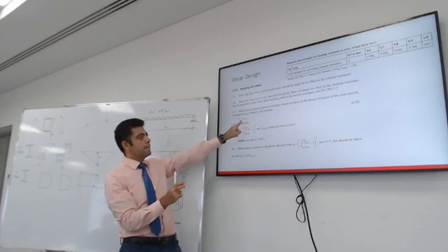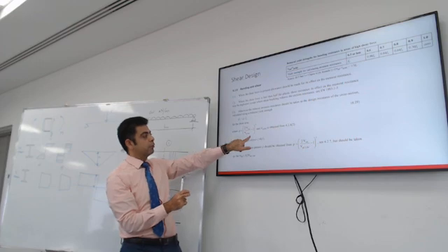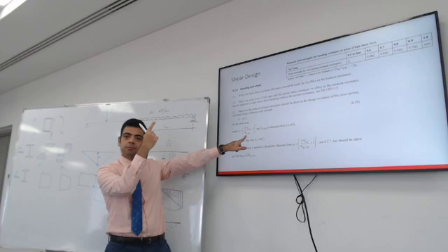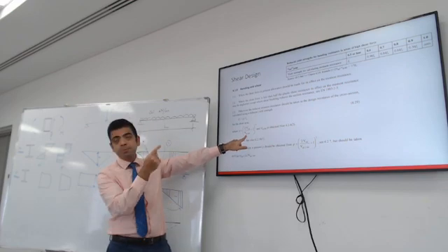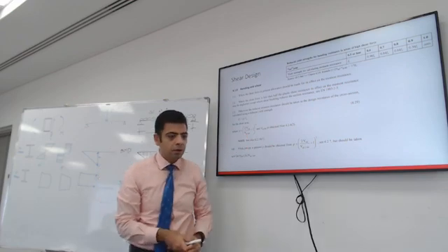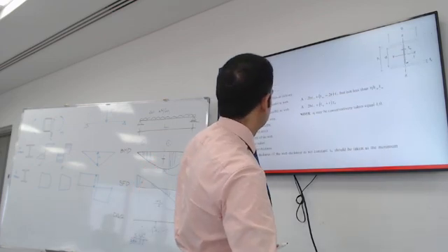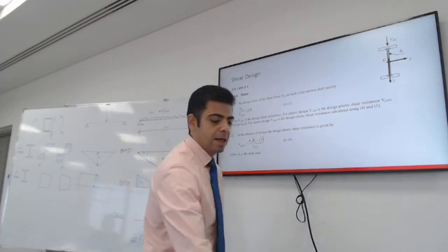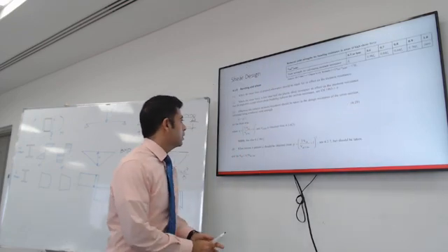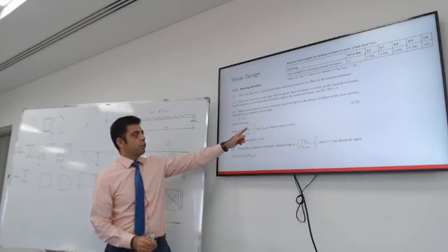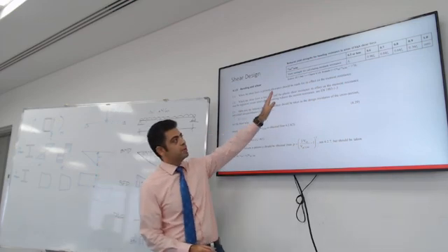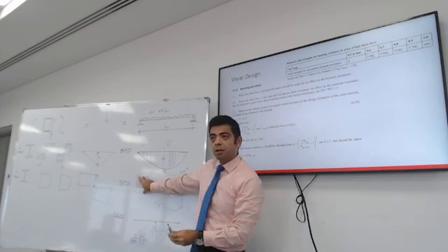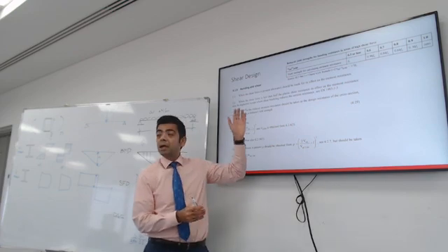So it's 1 minus a factor. You get the factor from the formula. It's the plastic shear capacity we got earlier from equation 6.18. You follow the formula with the square and everything, and this will result in a ratio between the actual shear and the shear capacity from the equation.